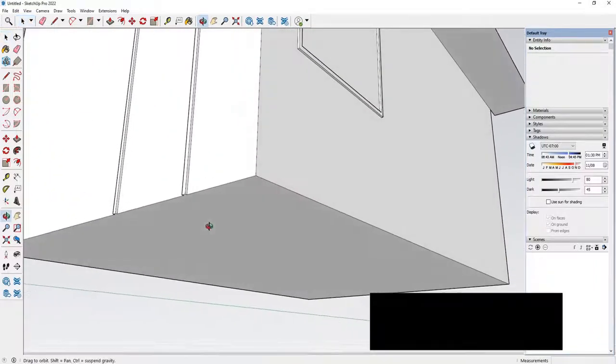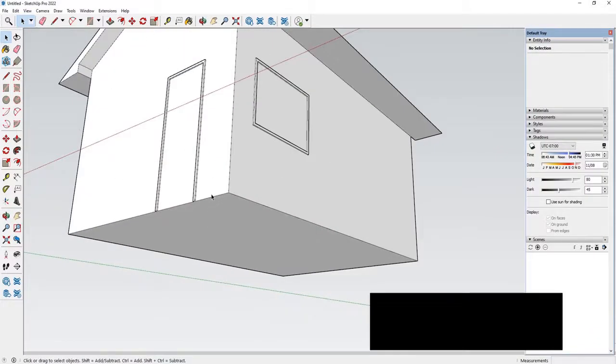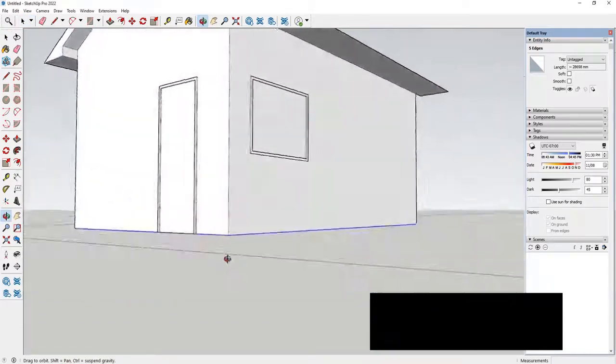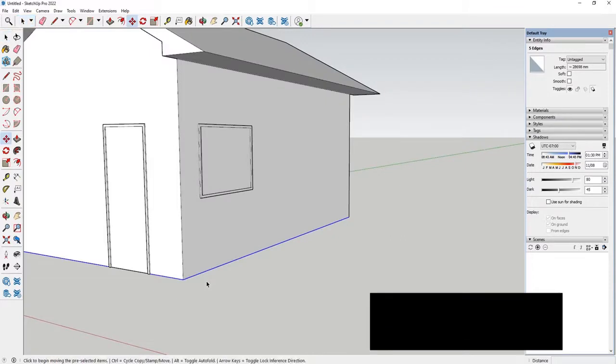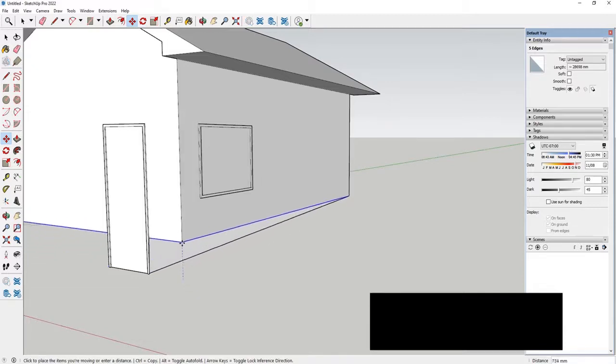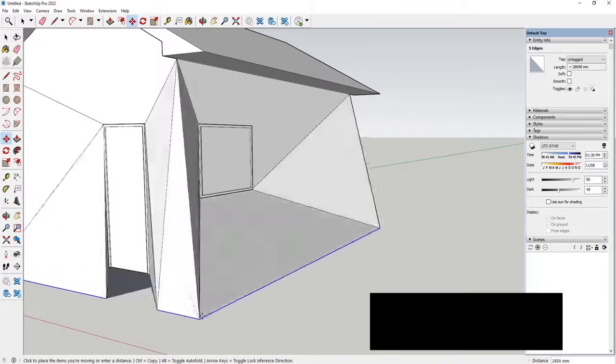First, we're going to go ahead and select all the lines that we want to do a move and copy of. Let's hold shift down and then left click each of these faces that essentially excludes the door or door frame material. And once we have everything selected, and it's looking something like this, then we're going to tap M for move. Now watch what happens. If I pick this bottom point and try to left click and drag, as you can see, it starts really warping the geometry. It's really not what we want.